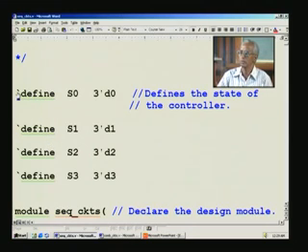And so you say define, and then here this indicates the state machine. Finally we will be seeing a state machine model, and in that we have used S0 through S3 for the states. So we can list all of this here, and while writing the code we can deal straight away with S0 and not the actual number. It is cumbersome to use a number at every point, so it is always easier to use a symbol like this, any meaningful name.